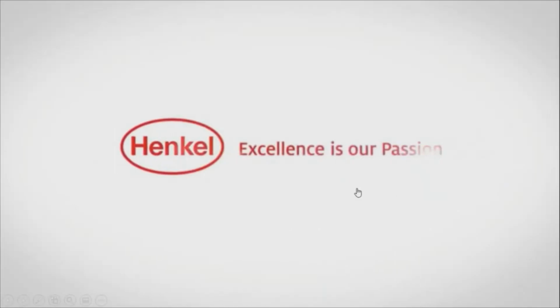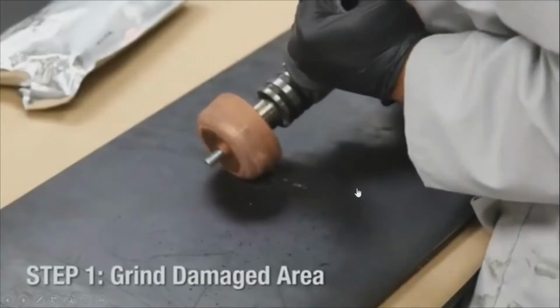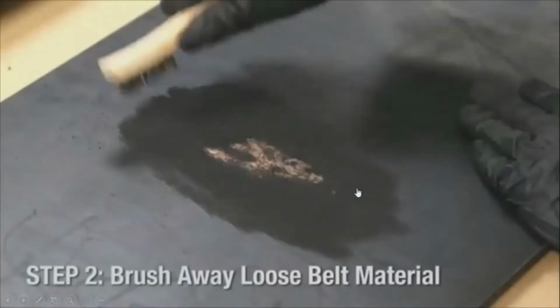Probably no sound, so I'll try to explain verbally. In any type of application, the first thing is surface preparation. In this case, the user is using a grinding machine to grind part of the rubber belt to provide a better surface for the conveyor belt repair.